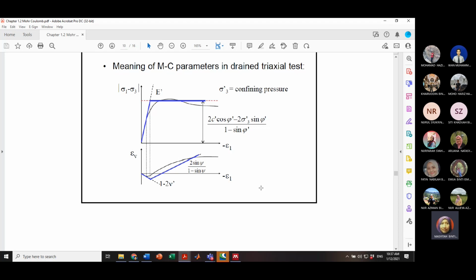So if you see from now on this slide, this is the real condition behavior of the soil from the experiment, in the black line, versus when you model it as a Mohr-Coulomb model. In this case the Mohr-Coulomb yield criterion is presented by the blue line. So logically you will see that the MC model is over-predicted, because it just takes assumptions close to the real behavior. However, it is not presenting the real behavior of the material.